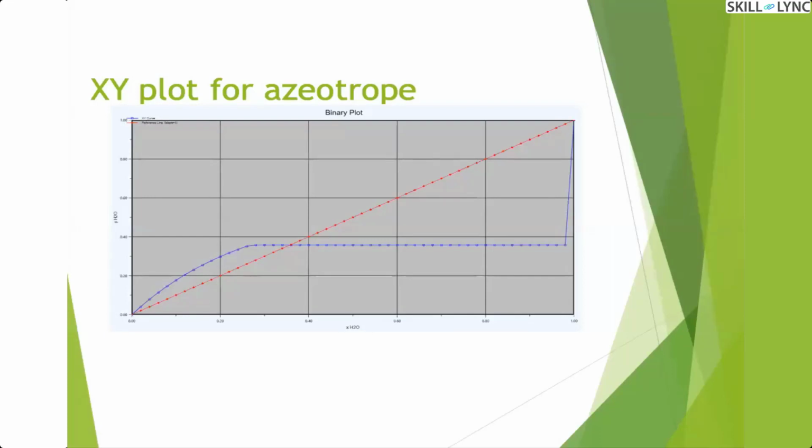So to have all those ideas, when you are going to start the distillation, the first step is to plot the TXY, PXY plot, and only then will you know the behavior of those components. So based on that, in the next step, using a shortcut column, you can have an idea of the number of stages. What a shortcut column does is, you would have all read about the Fenske-Underwood equation during your college days.